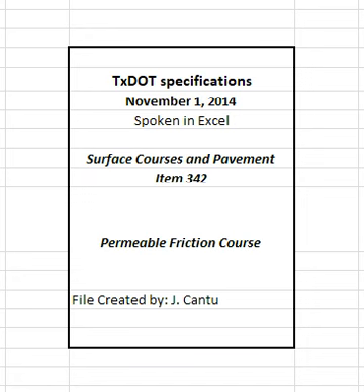2.6.2 RAS. Use of post-manufactured RAS or post-consumer RAS, tear-offs, is permitted unless otherwise shown on the plans. RAS is defined as processed asphalt shingle material from manufacturing of asphalt roofing shingles or from re-roofing residential structures. Post-manufactured RAS is processed manufacturer's shingle scrap byproduct. Post-consumer RAS is processed shingle scrap removed from residential structures.